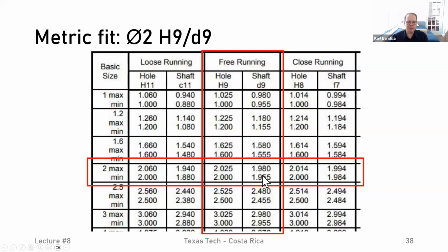Now, based on this, is this a hole or a shaft-based system? A hole. Why hole? Because the basic size is in the limit of the hole, exactly here.